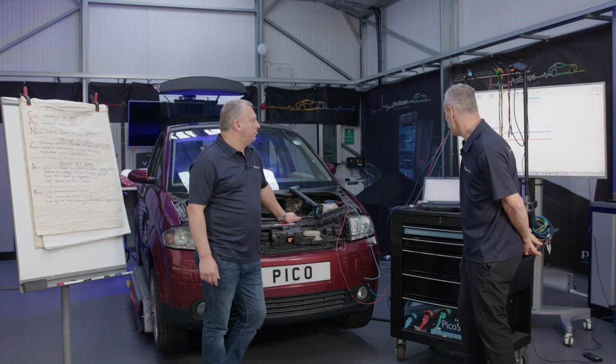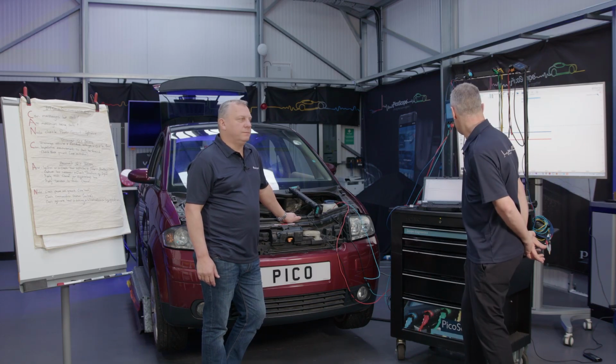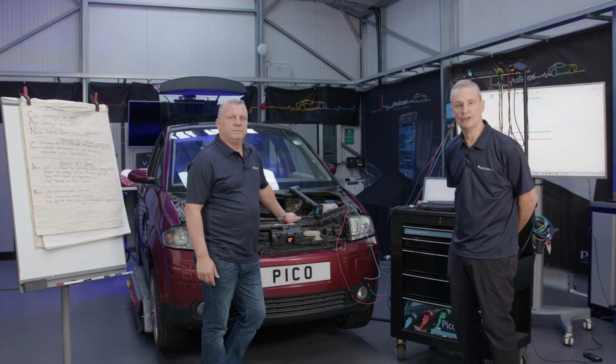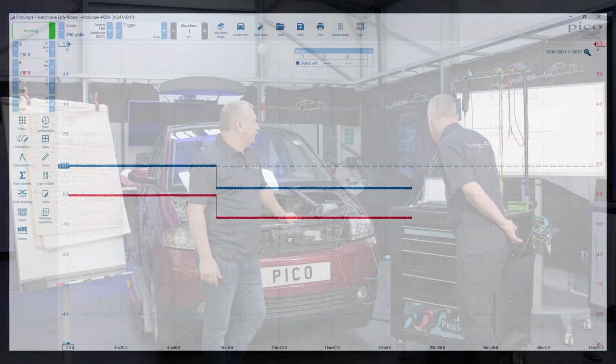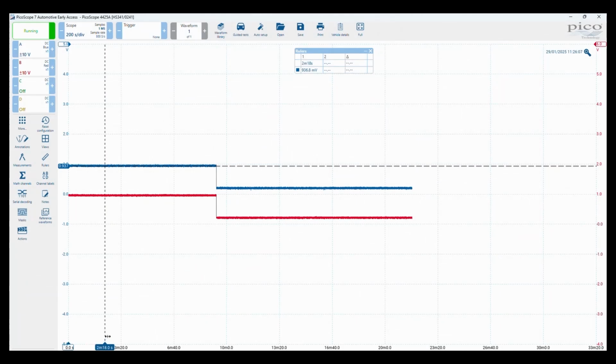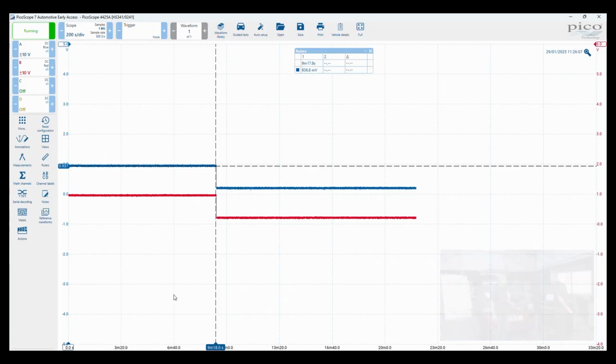Okay, so we have come now down from the standby voltage to what we believe to be the sleep, which is kind of, again, another revelation here: we were expecting 0 volts. It may be that if we left this capture running for longer we could see it drop, but first of all, we'll have a look at where we left off at 900 millivolts. The time span was 9 minutes 17, so we did throw out sort of 10 minutes, 20 minutes out there, but that could vary depending on environmental conditions as well and vehicle operating conditions.